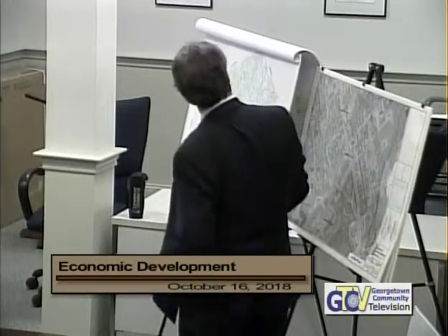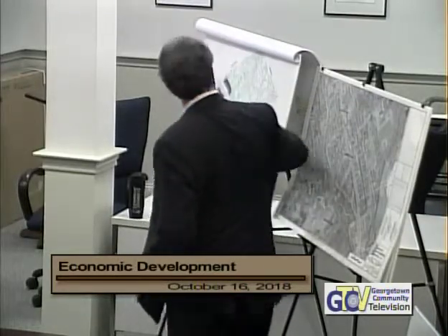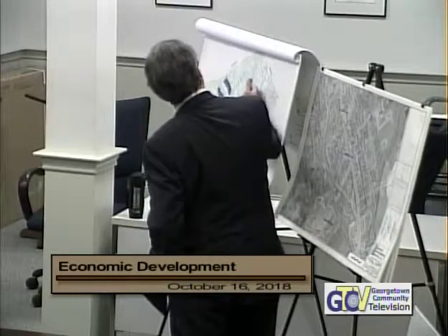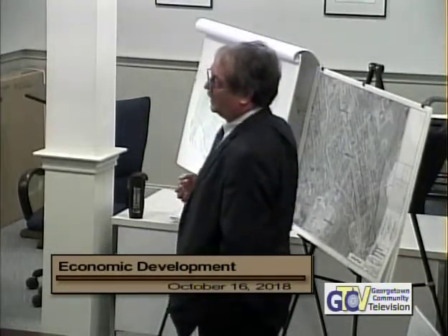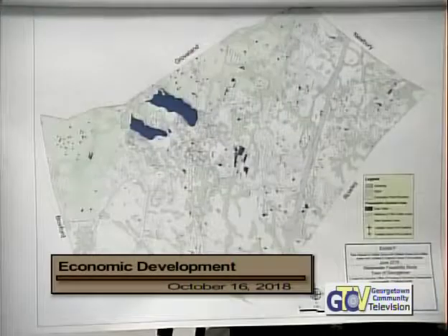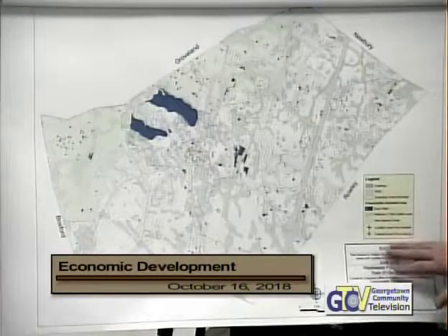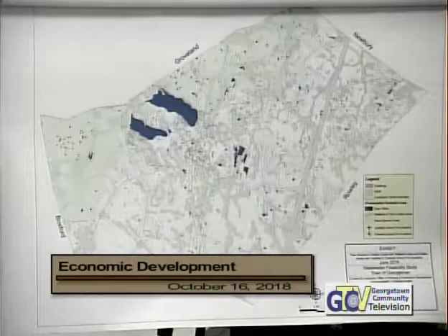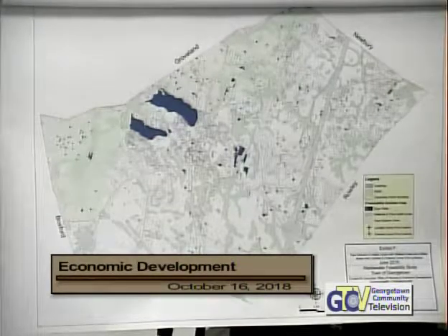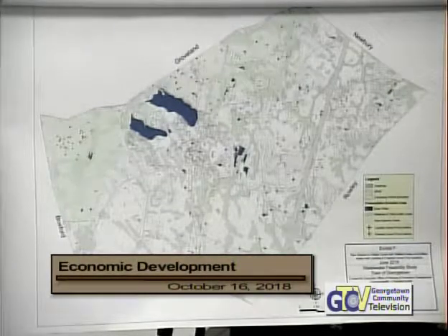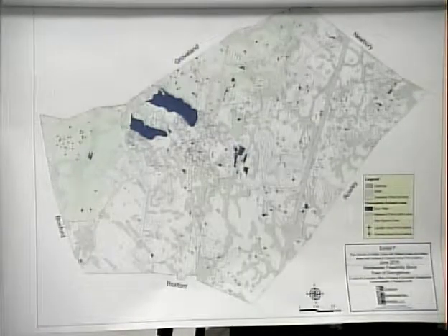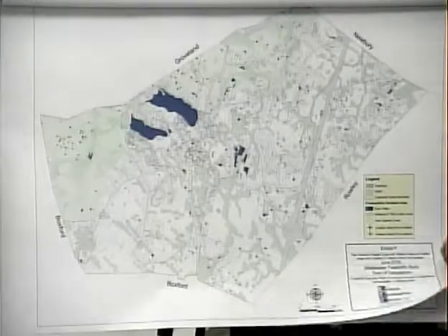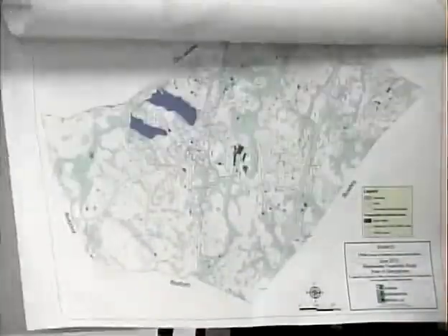The other aspect was basically, and you can't see it from there, obviously, but we have a bunch of X's in here. And this is basically vernal pools, rare endangered species habitat. Those also have a large potential to restrict what we can do in some of these areas. The offsets to these areas are much greater than they would be to a normal wetland area, and they tend to restrict lots as far as feasibility. So we also consider that when we're looking at a lot of the lots in the system.